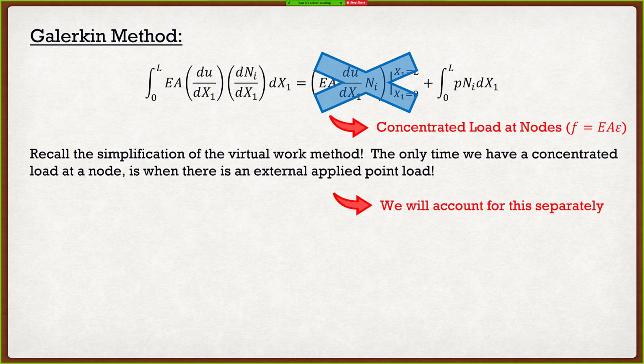The reason why is that if we're dealing with finite element analysis, as you are going to see, one of the biggest things we have to be aware of is computation time. If I were to keep that term in, it's fine. It won't change anything. The only difference is I'm going to be calculating a load going this way, and once I get to my element over here, I'm going to calculate the same load going that way. They're going to cancel each other out. So if you include that term, you will get the same answer. It's going to be no problem at all. The only problem is that you are just going to be wasting computation time.